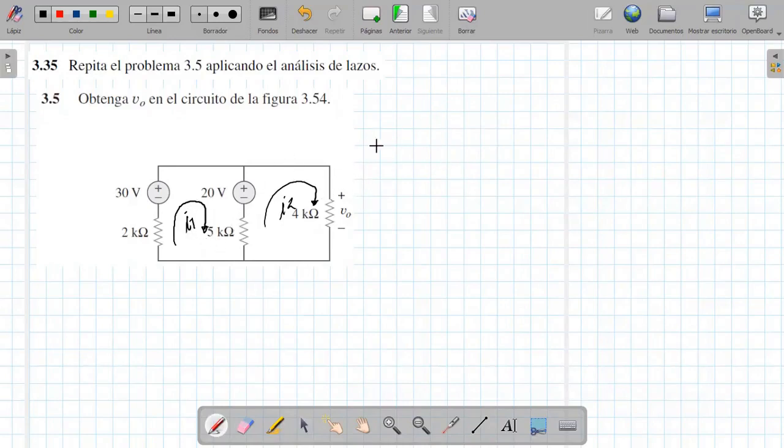Let's remember that when we did node analysis, they were voltages over resistances. That was current, but in the end the equations are in terms of voltage and we find the voltages because we use the KCL principle. In loop analysis, we do this analysis of voltages, which is current through resistance, and since the equation will be in terms of current, we end up finding those currents.